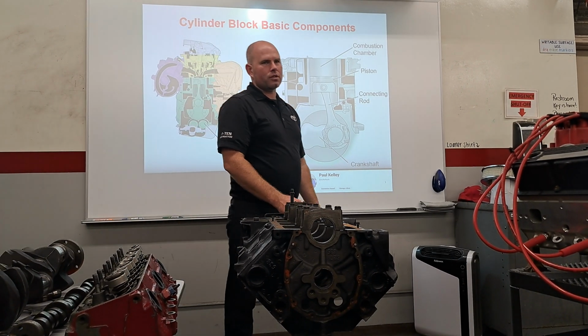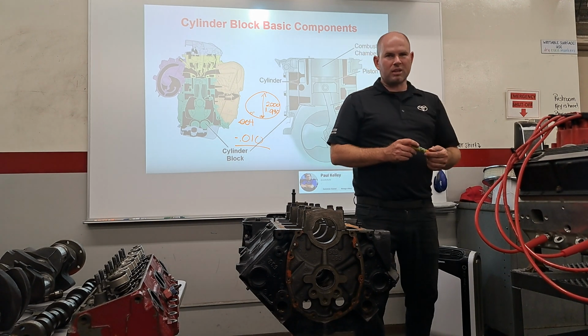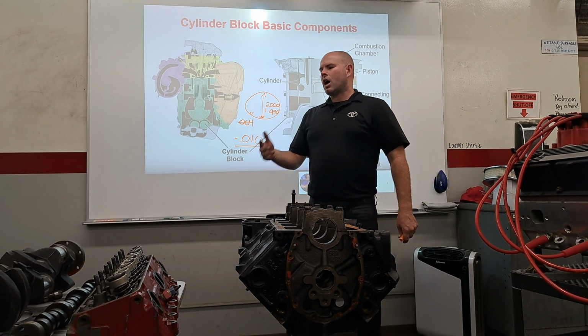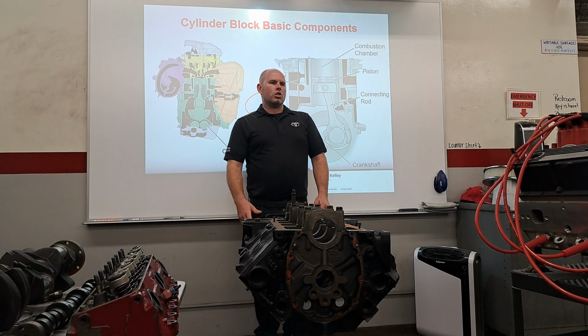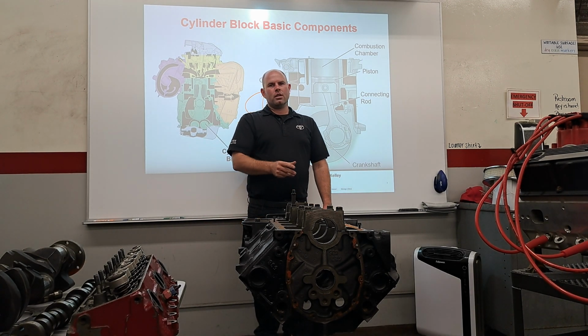Does that make sense? So you're going to see that's a common theme in engine work. You don't just machine it till it looks good like a rotor. You've got to cut it to a number. And that way you're going to have the right clearances, etc.